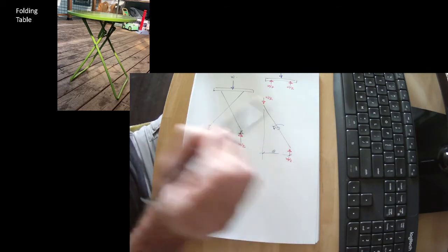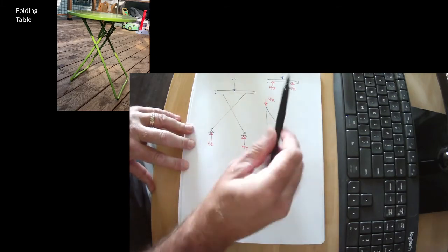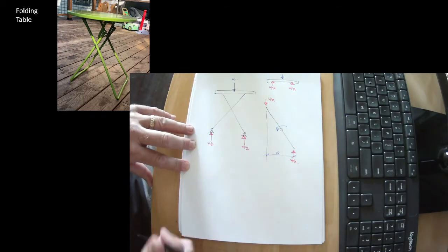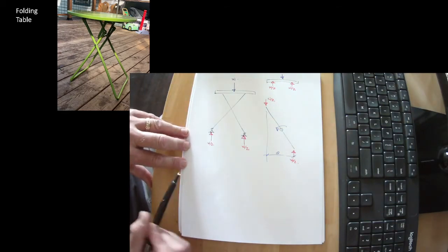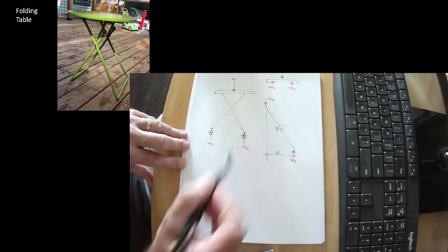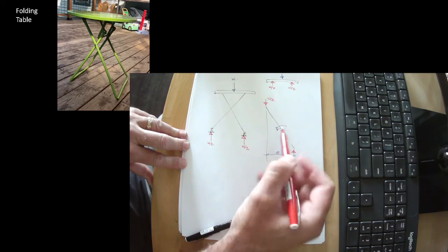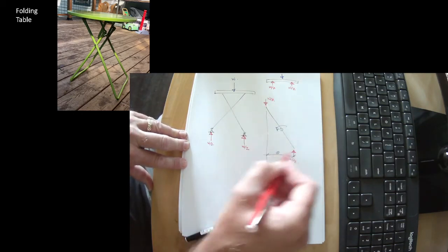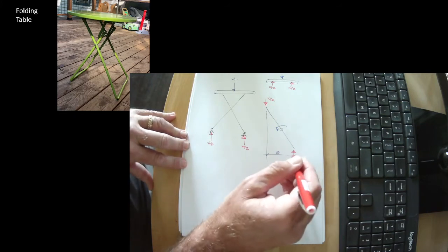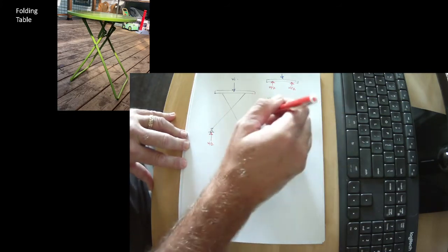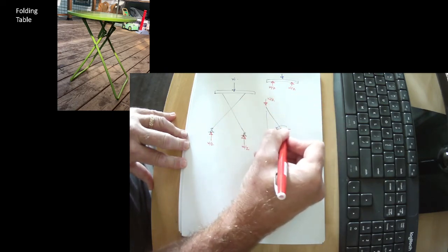That means that we can't have a vertical force. Because if we have a vertical force up on this leg, we need to have a vertical force down on the other leg, and we're no longer in equilibrium. We're not balanced. So we can only have a horizontal force on this. So what we wind up with in this diagram, we know that the reactions are tending to make it rotate this way. We need forces to make it rotate the other way.